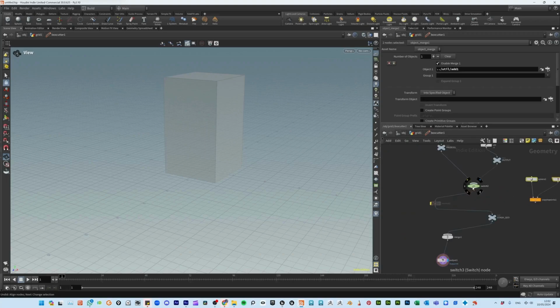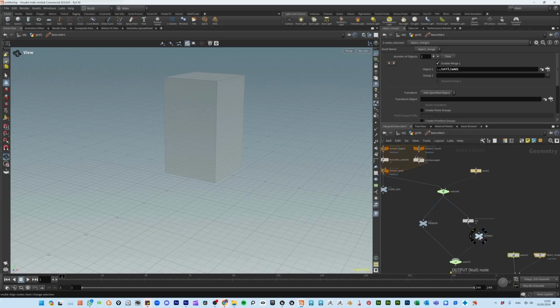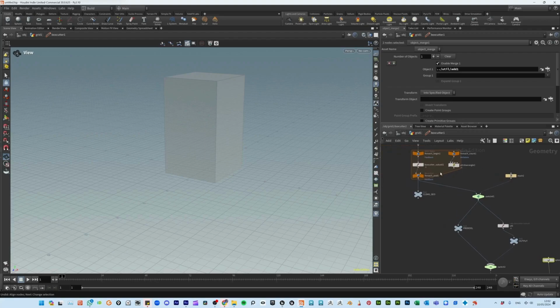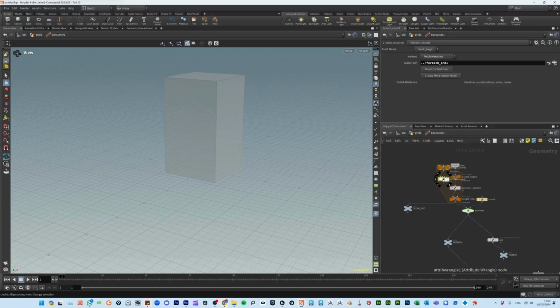If we want all of these nodes arranged down, we can take this node, without selecting anything, press A and drag down, then it takes everything down. The same way I can drag everything up, but in this case I have a lot of things that are not connected. It won't look as good. It just looks a bit messier, but we can still use it as a starting point to arrange our network.